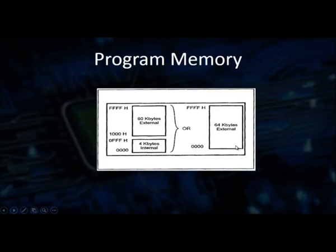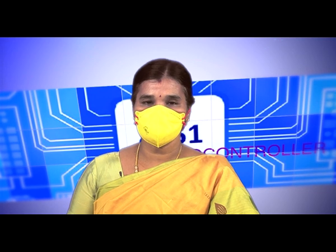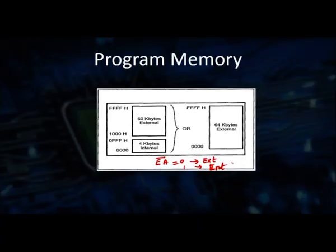Whether you are using the internal or external memory depends on the EA bar signal. When the EA bar signal is 0, you can use the external memory. When it is high, you have to use only the internal memory. In the 8051, the internal ROM of 4 kilobytes is available. So, 4 kilobytes means its maximum address is FFFH. 4 kilobytes represents 12 address lines, so a maximum of 12 address lines are available.